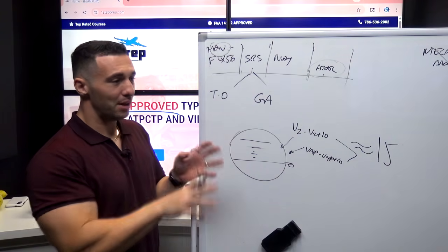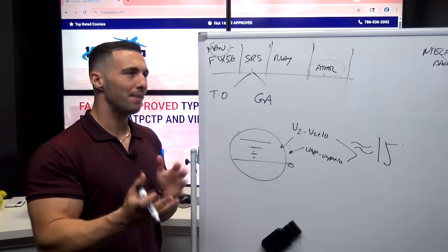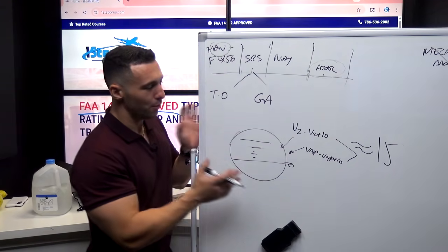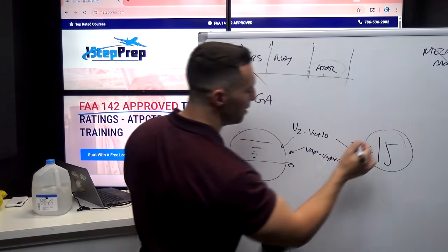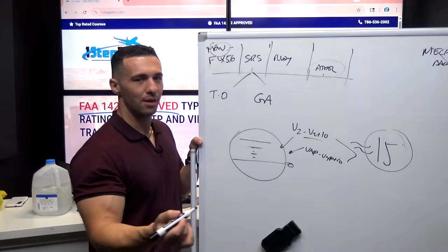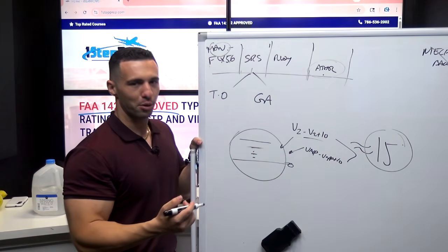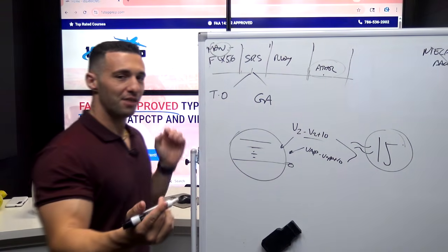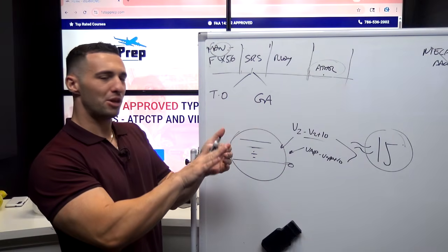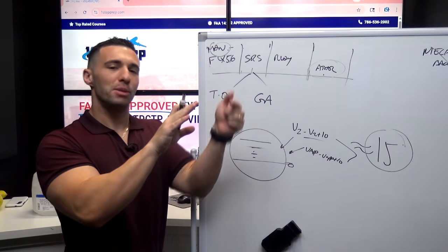And then everybody says, "No, you said it's going to go to 15 degrees, but actually it's up at 17 degrees." Yeah, it is temporarily. Remember, it's actually not pitching for a degrees of pitch. It's pitching for an approximate pitch attitude that would give you V2 to V2 plus 10, or VAP plus 10 as appropriate. And it's realized that you have exceeded the speed because you delayed the rotation a bit. So now it starts to pitch a little bit higher to bleed the speed.